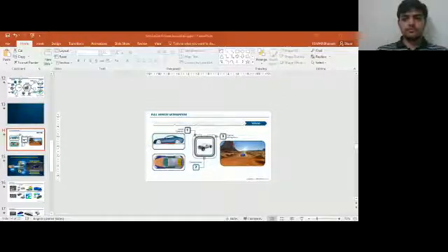If you're into mechanical engineering and you have taken theory of machines or something similar, where you work on mechanisms, the way you build your equations and solve them is precisely the way SimPack works. One of the advantages of that method is that when your system becomes complex, like a full vehicle, SimPack will be able to solve it because the number of equations doesn't really increase that much. So this allows us to go into real-time analysis of vehicles.